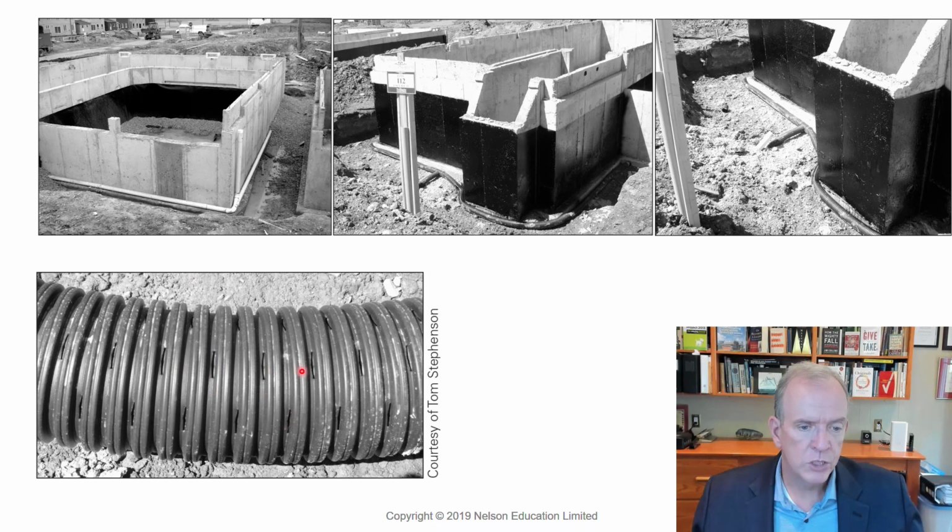It has all these serrations in it, and that means that when it's placed around the footings and moisture builds up through the filtering through the gravel, it will be able to take that moisture away. Then this connection here is actually connecting up to the storm drain for the house, and the storm drain is going to go into the drain on the street and take it away.